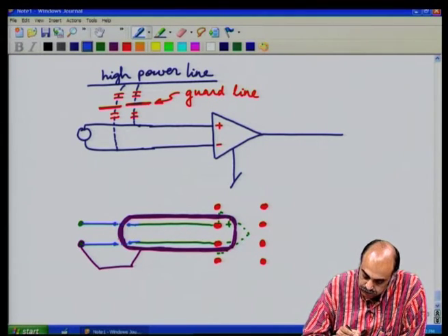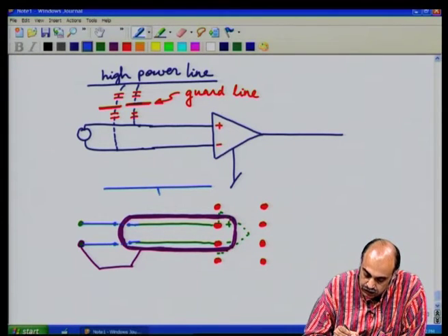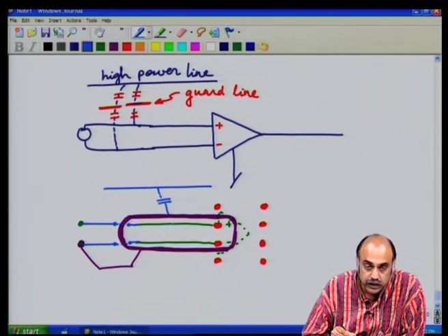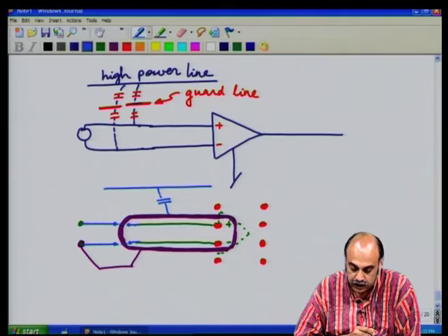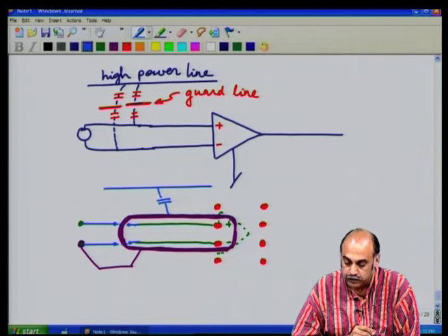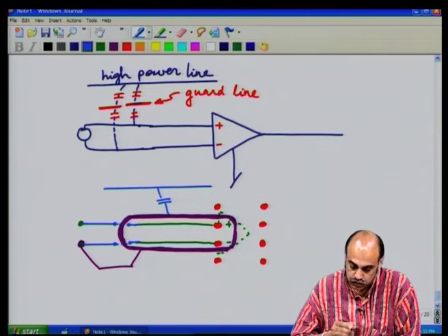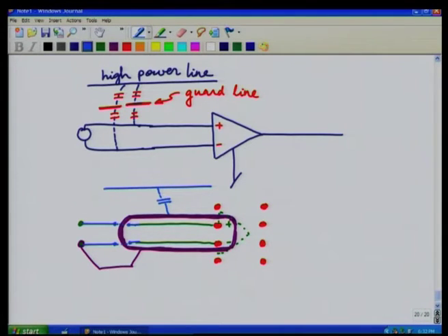Now you see these lines are guarded from any external line, which has capacitive coupling to the guard, but not direct coupling to the two lines of the differential amplifier. This will improve the performance of a high precision difference amplifier to a great extent. You should use the guard concept not only here, but even in high frequency cascode stages, to reduce the capacitive coupling effects on the various amplifier stages.